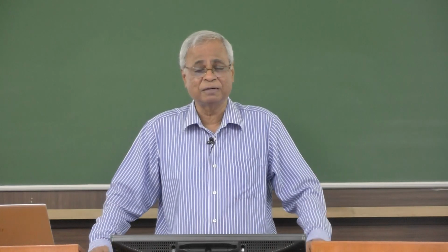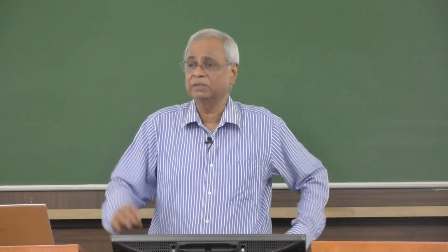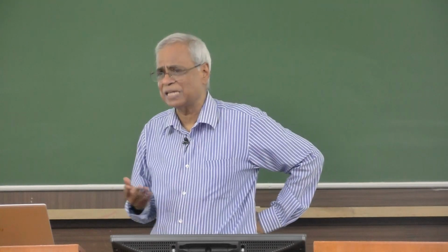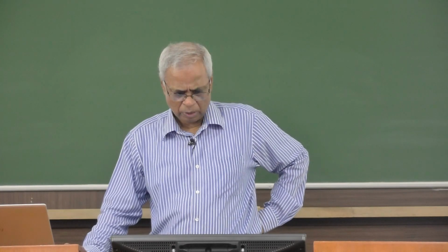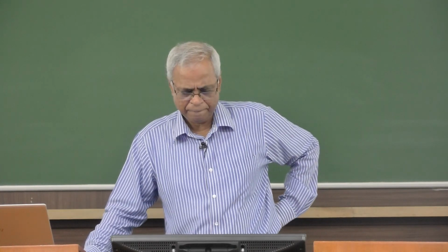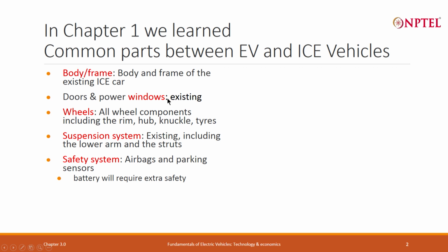vibrations due to the moving parts will be small. Can you change the material used for body? Well, that is just something that work has just started and it is a future thing. Similarly, doors and power windows pretty much existing. Of course, you will probably not have manual, you will have all with motors, which requires electricity, which a separate battery was used in a petrol vehicle. Today, you do not need that separate vehicle battery. You will take the existing battery, convert it to the right voltage and drive all these motors for windows and doors and things like that.